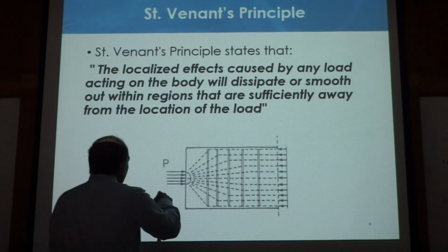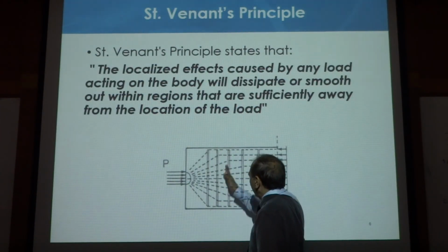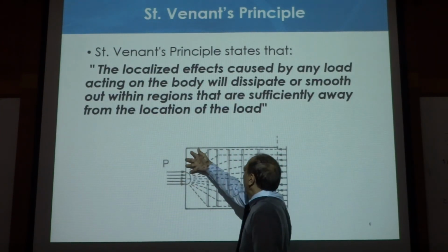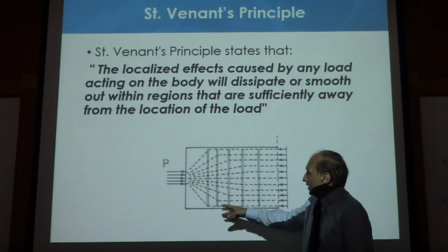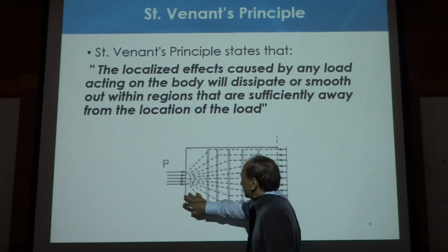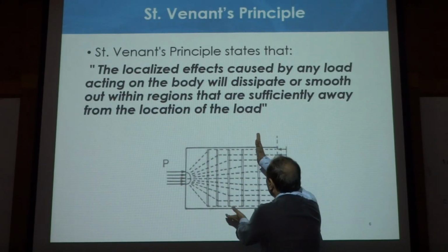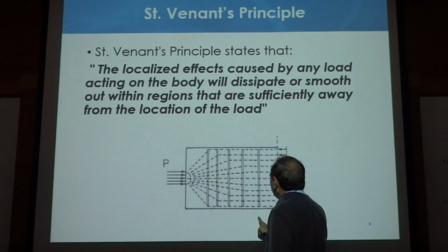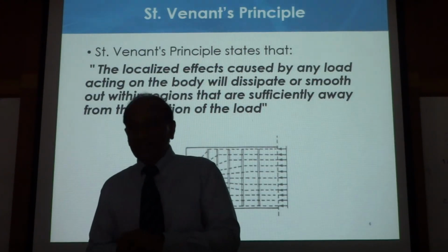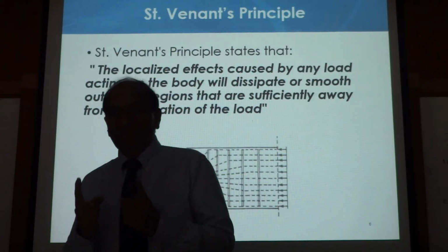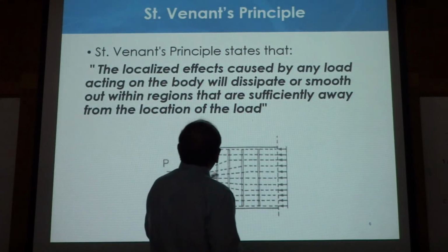And so if you put a high force here, then after some time the force will become uniform, as if it was applied uniformly, right? At this location, the stress will become uniform. Here there will be no stress or negative stress, tension maybe. Here there will be very large stress, and it will spread like this, and then after some time, at a certain distance from this location to this location, it will become uniform. This is a very important and interesting observation. So now we have two things to look at: one is Bernoulli's theorem, and second is Saint-Venant's principle.